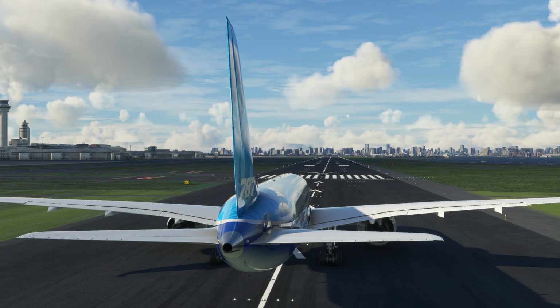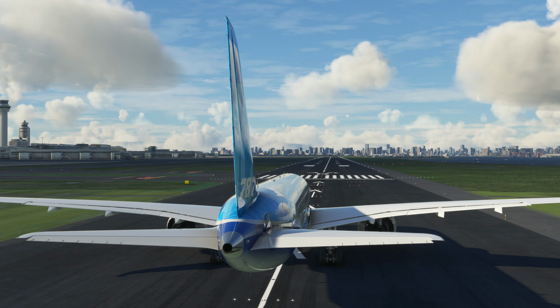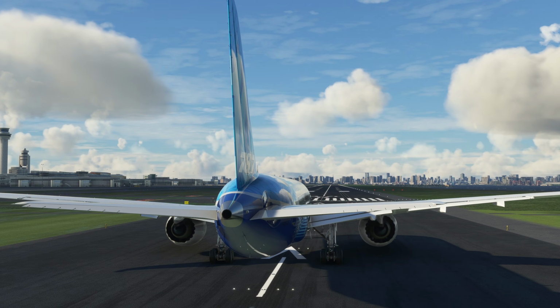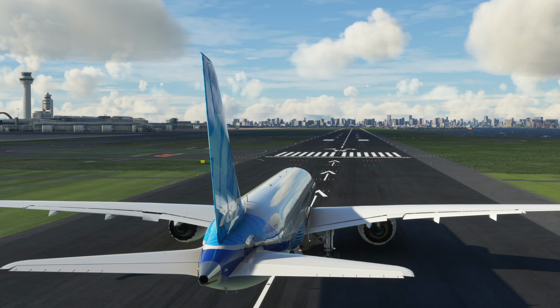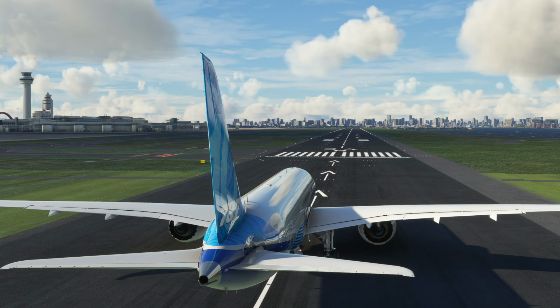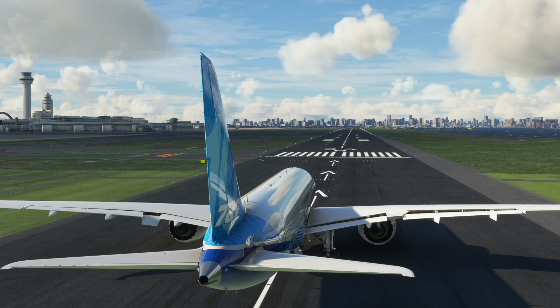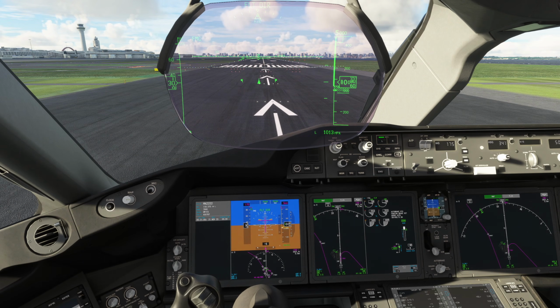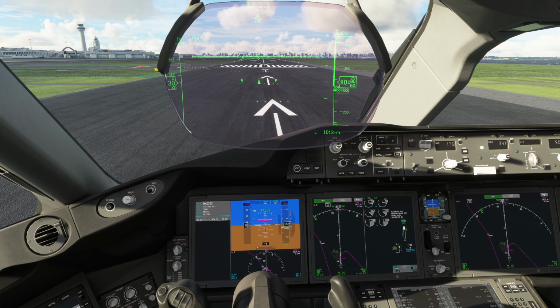So like I say, same on the yoke, we still just put the yoke a bit forwards to help with directional control on that nose wheel, and then we're going to have a bit of into-wind aileron and increase that as required to keep the wings level. As we get to rotate, we're going to rotate the aircraft as normal, but we're going to keep the rudder as needed and the yoke as needed, so that the airplane eventually takes off in a bit of a side slip position, and then once it's in the air we can smoothly return those to center and let the airplane weathercock naturally into the wind, and then we're away, and that's pretty much it.